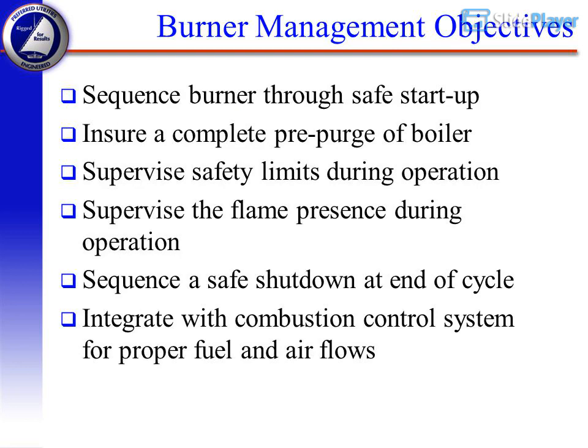Burner Management Objectives. Sequence burner through safe startup. Ensure a complete pre-purge of boiler. Supervise safety limits during operation. Supervise the flame presence during operation. Sequence a safe shutdown at end of cycle. Integrate with combustion control system for proper fuel and air flows.